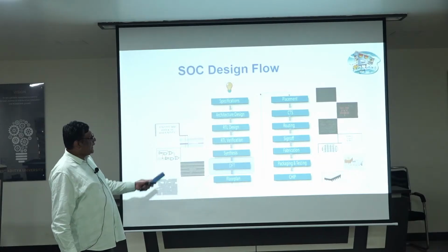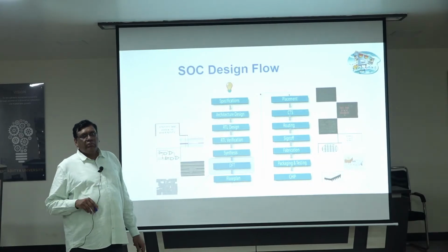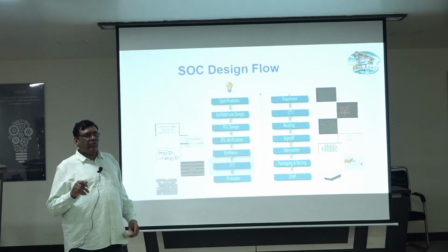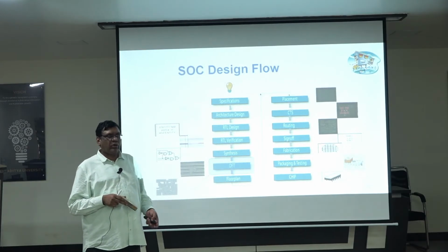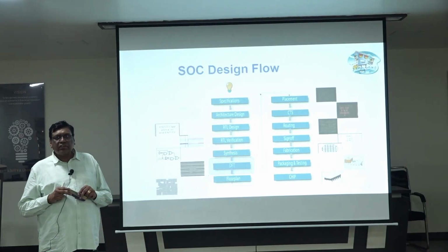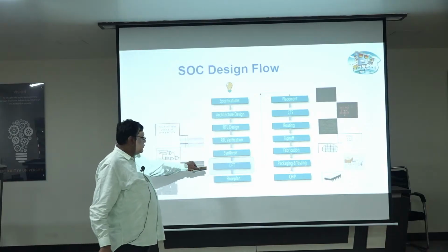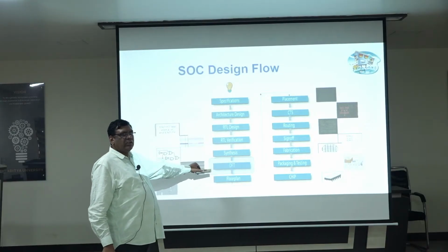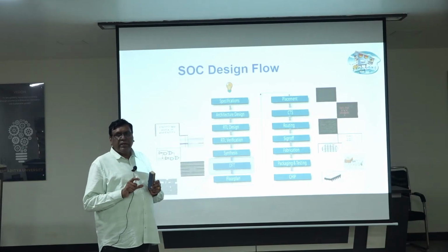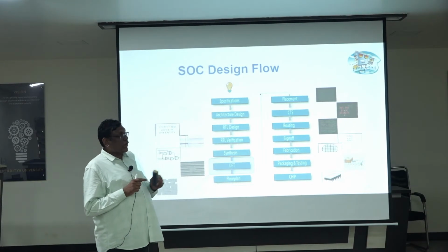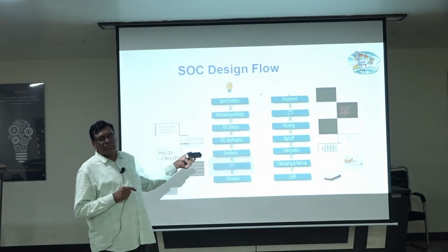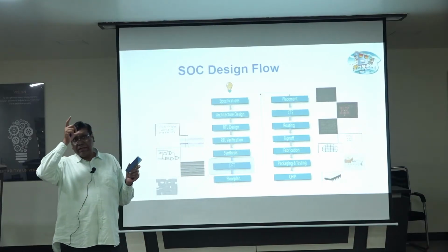Then floor planning, where the layout will be formed. Maybe some of you are exposed to layout designing; I am not aware of that. We will draw layouts of the transistors, so that layout conversion has to happen. For that, floor planning is needed, the placement of each and every subsystem has to be defined, along with the connectivity between them, and clock tree synthesis is the most important part. I am not going into more detail on this because I want to cover the actual DFT techniques.